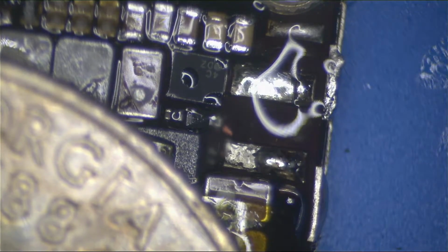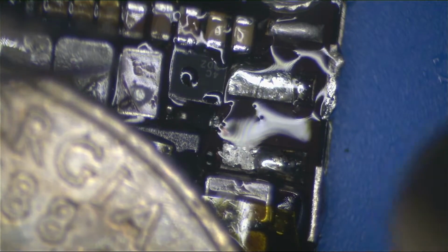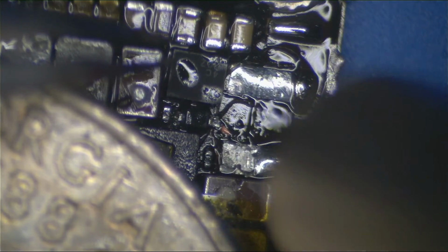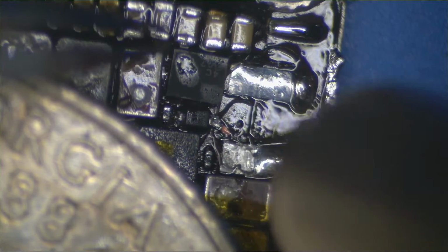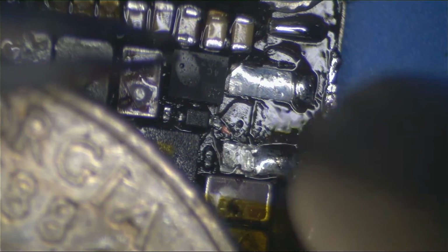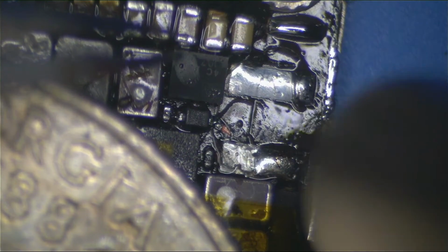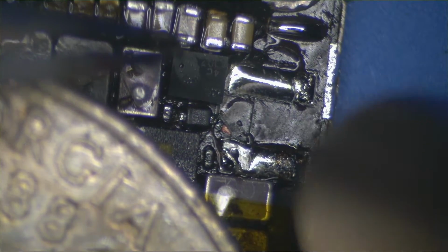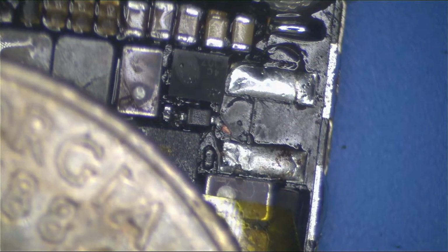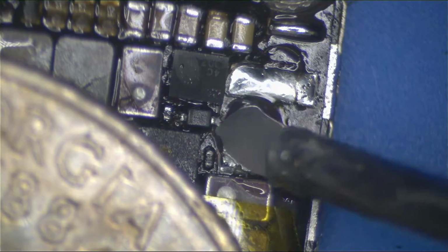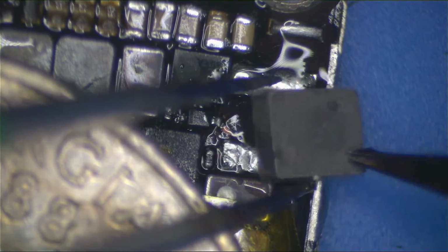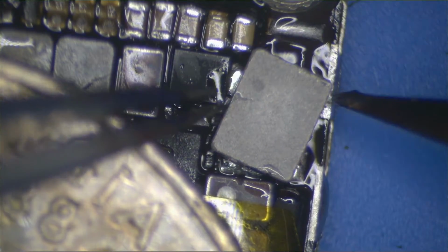Now just come in with your hot air and gently warm it up. So just wait for those pads on the coil to start to turn shiny. Now, if you tin these with leaded solder, it'll melt pretty easily like that. You see, they both just float a little bit, so they're a little bit more even now. And now you can just add some flux and stick your coil down, and you can flow both the driver and the coil into place at once.